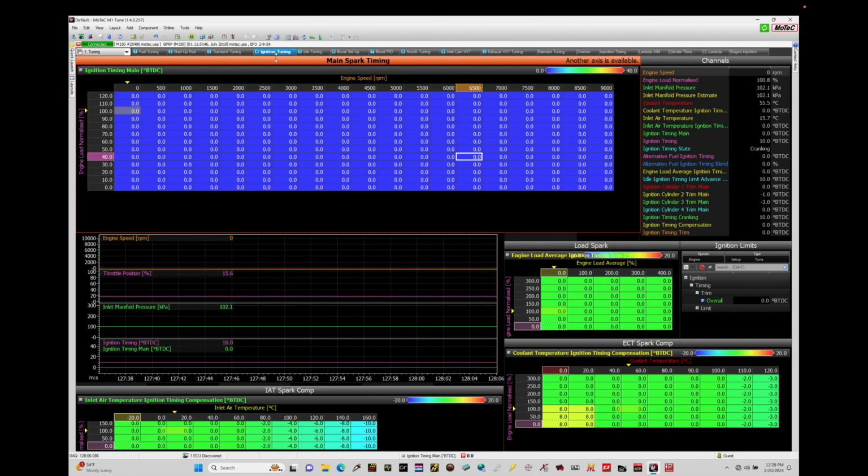We want to put reasonable values in here that are safe, that we can get things calibrated, that aren't going to put us into a dangerous condition, so we don't want to worry about knock or pre-ignition. Looking at my table, this table is going here from 120 to 0 in engine load normalized. Now my engine load normalized is utilizing my inlet manifold pressure sensor, or the MAP pressure sensor, for the table input. I also set the table up here going out to 9,000 RPM.